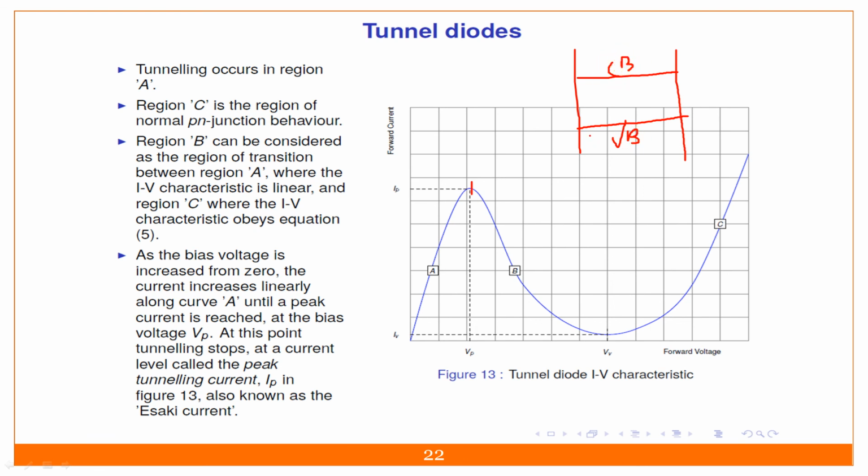Due to this, the electrons are caused to flow from the valence band to the conduction band. But from this point up to this valley point, the electrons in my conduction band are shifted to the third band. If the electrons are shifted to the third band, they become somewhat sluggish and are not conducting the current. Their drift velocity decreases, which means an increase in the resistance.